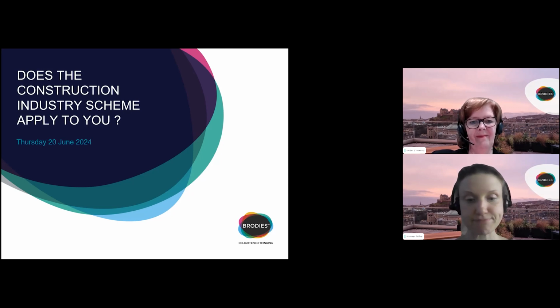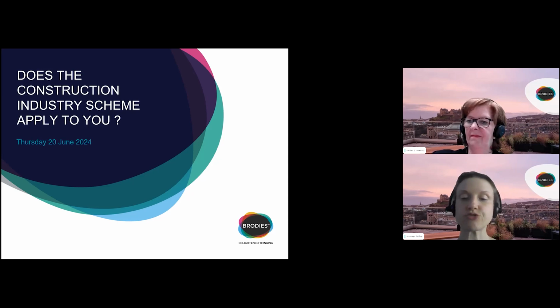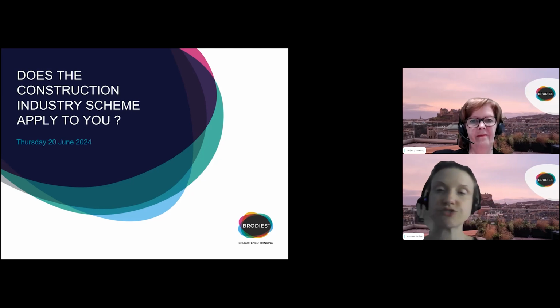My experience is there's a lot of assumptions about CIS, and these are not always accurate, so Isobel is here to set us straight. In the construction team, we deal with contracts across a wide range of contractual forms, from bespoke contracts to using standard forms like JCT, SPCC, NEC and FIDIC. And it's in relation to the JCT and SPCC forms that we tend to encounter queries relating to CIS. And that's because there's an entry in the JCT and SPCC contract particulars that needs to be completed, confirming whether the employer is a contractor for CIS.